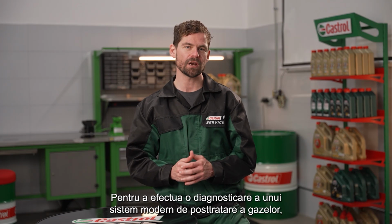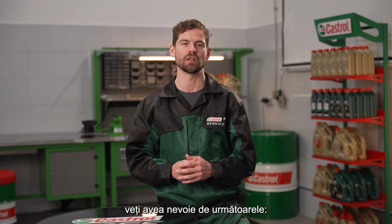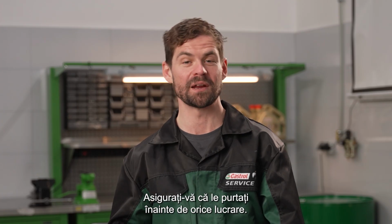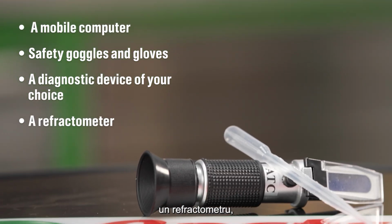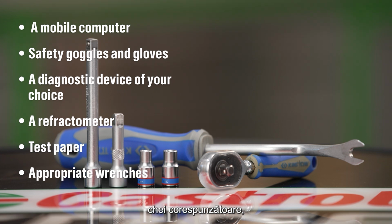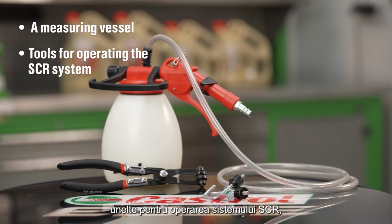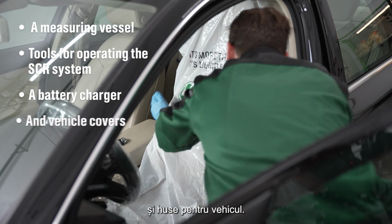To perform a diagnostic test of a modern exhaust after-treatment system, you are going to need the following: a mobile computer, gloves and safety goggles. Make sure you wear these before doing any work. You'll also need a diagnostic device of your choice, a refractometer, test paper, appropriate wrenches, a pressure gauge with adapters, a measuring vessel, tools for operating the SCR system, a battery charger, and vehicle covers.